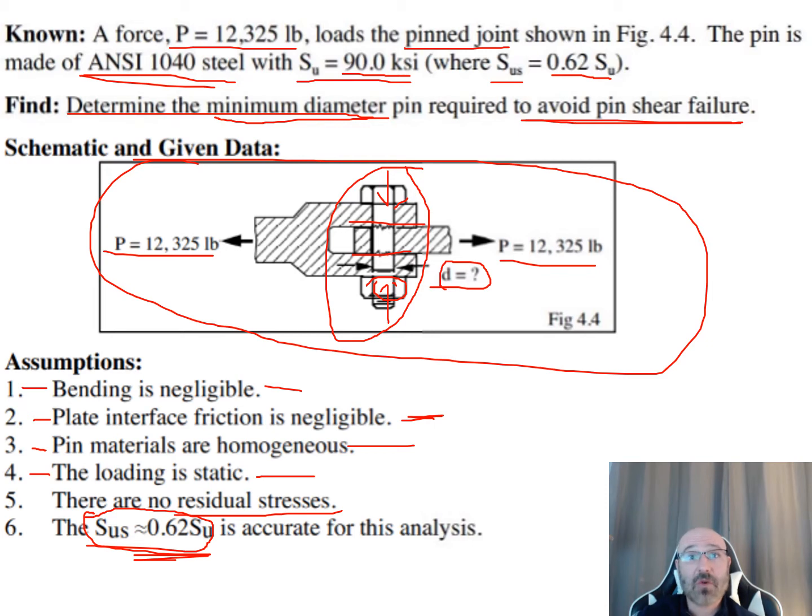We have this torque spec here, and what is the load applied from it, and how does that load affect our coefficient of friction? Then we can pull sideways and say, okay, we have our coefficient of friction times our normal force pushing up on that. How does that affect everything else? Those are all things we need to consider, and we'd have to do a whole free body diagram for that. We're not going to do that, but I want to address it so that as you apply this to your actual group projects for the end of this semester, this is something you do need to consider.